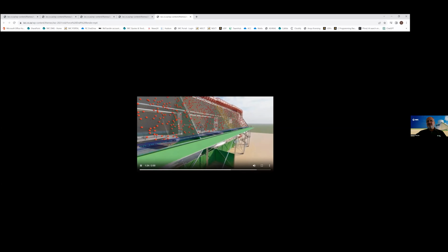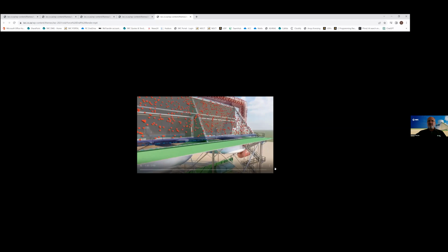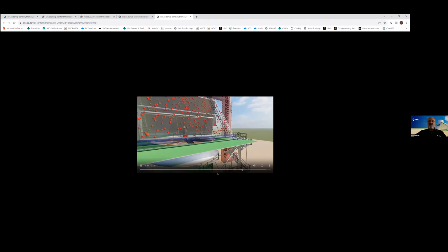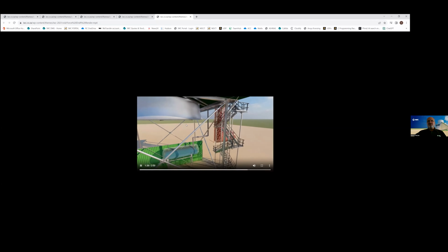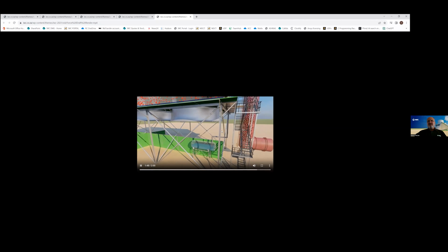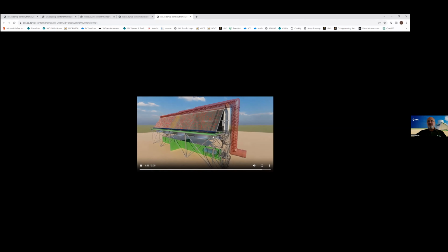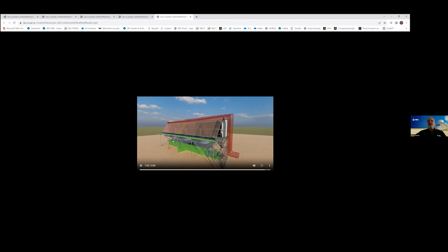So this liquid water then drains into this condensate tank at the bottom here. And this is a forced draft arrangement. So the air is blown in from the bottom, the fan is below the heat exchangers, so it blows the air through the bundles. And this is the technology that's been used up to recent times, I think up to about 10 years ago. And it's often preferred due to the track record and the fact that many references exist on this technology.